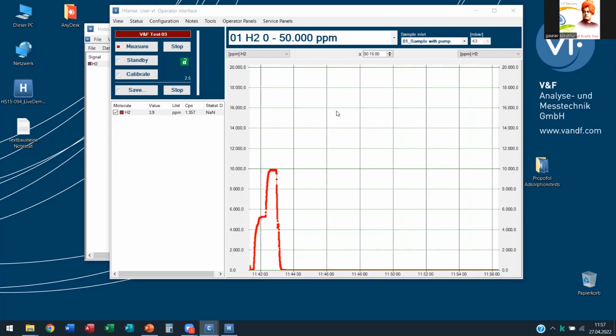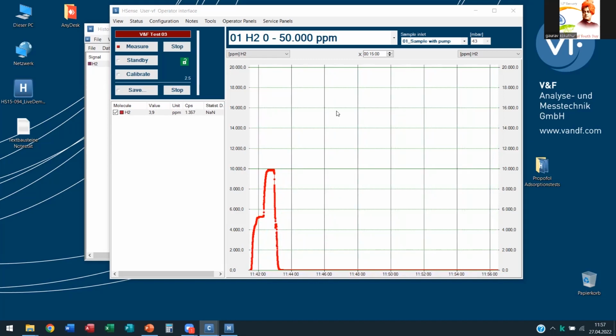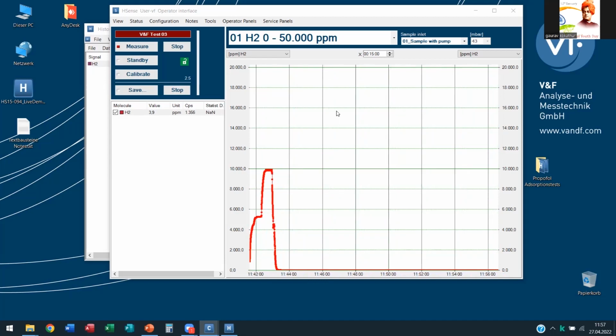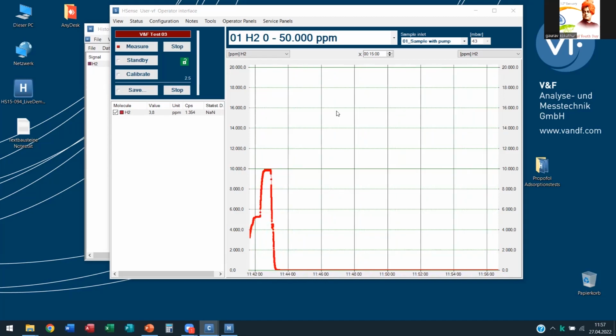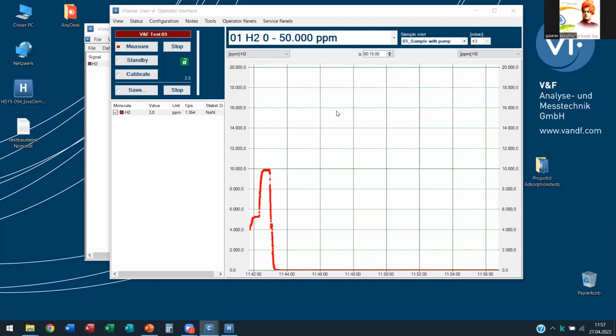Otherwise, you may not get measurement accuracy because of the dirt and dust in the line, or you may not get a sufficient sample pressure when you are measuring. So in order to avoid those things, there is an option called purging in most exhaust analyzers. I was just comparing in that way, and I was asking if there is any such option given in your system?